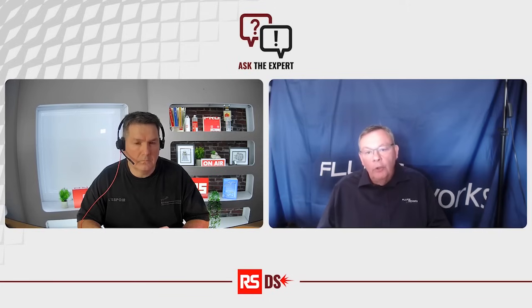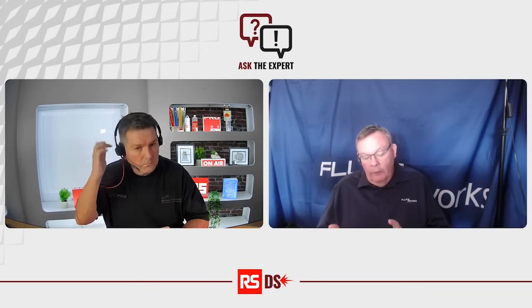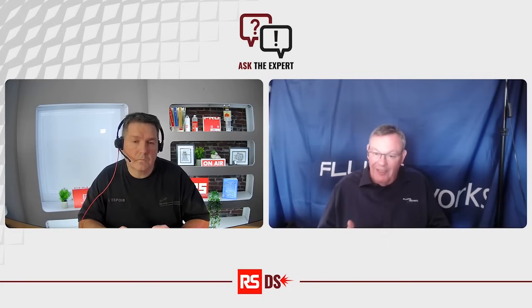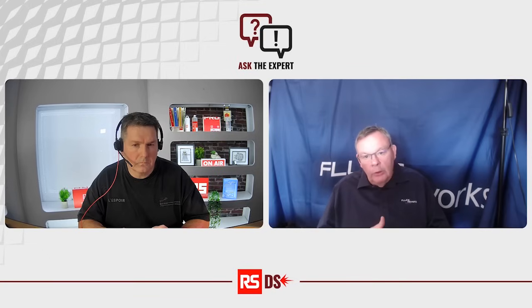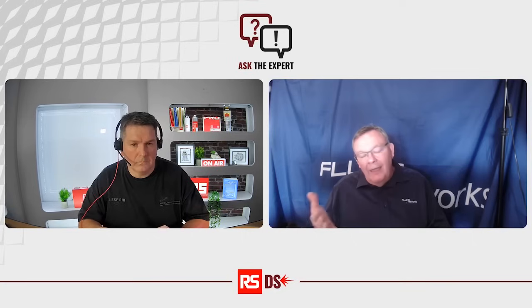and we can then move on to having tested the cable and confirmed its bandwidth, we can then plug it in at the switch end, and going back to the camera end, we can confirm that we have network connectivity. We can see the switch. The switch responds to a query from LinkIQ, and we can also confirm that the switch is delivering the required amount of power over Ethernet. And we get clear, unequivocal test result data that shows all of that.